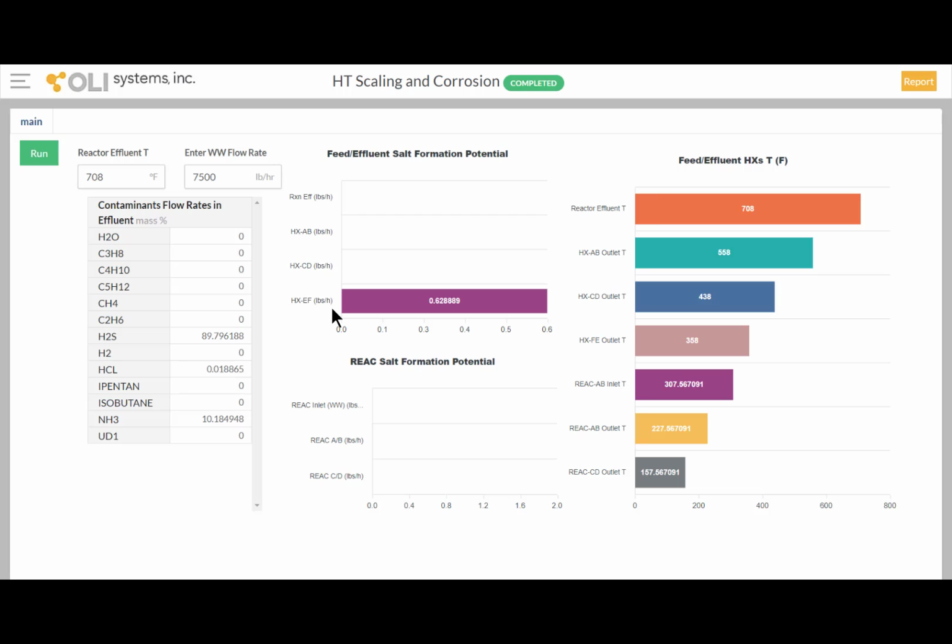So for example, a diesel hydrotreater of about 12 to 14,000 barrels a day, based on current market conditions, could save anywhere from $5 to $8 million, depending on the length of the shutdown, if they don't take an unplanned shutdown and all they do is that targeted chemical cleaning to recover heat transfer and go all the way through their planned turnaround. And you can do this a couple of times through the life of that cycle. Yes, your chemical injection cleanings won't be as effective as the first one, but it'll allow you to get to that point without having to take that unplanned shutdown and lose the opportunity to make that money.